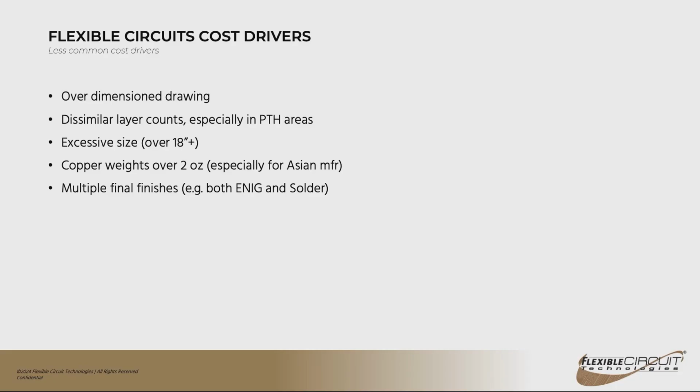And if it's an SMT connector, the stiffener goes on the backside. If it's a through-hole connector, the stiffener would go on the same side as the component, and then the component leads would go through the stiffener and then be soldered on the backside to the flex.